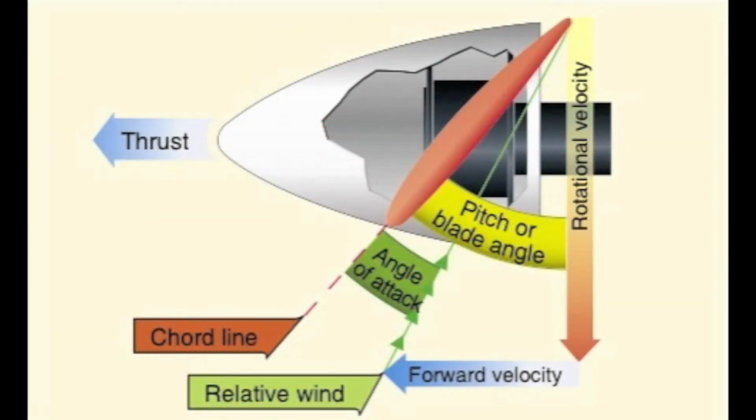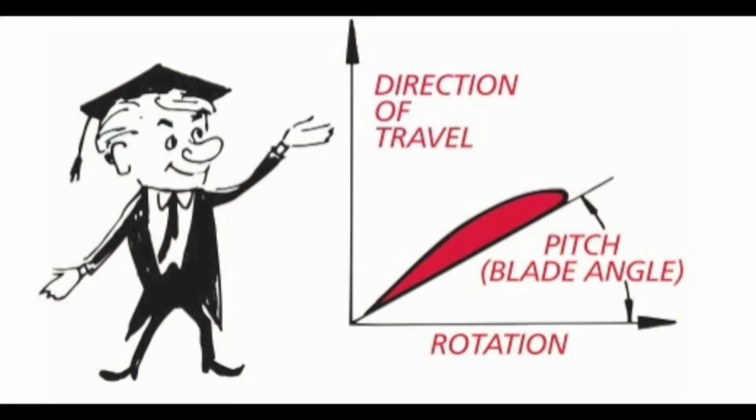Before we learn how this governor changes the blade angle of the propeller, and therefore the pitch, we need to first learn how the propeller angle is moved. Also, to further simplify our discussion, since changing the blade angle directly changes the pitch, I will use the term pitch to mean changing the blade angle for the remainder of the discussion. Again, anytime we change the blade angle of the propeller, we are changing the pitch of the propeller.